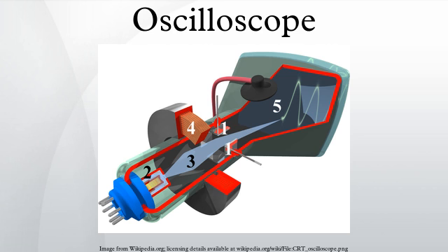A digital phosphor oscilloscope uses color information to convey information about a signal. It may, for example, display infrequent signal data in blue to make it stand out. In a conventional analog scope, such a rare trace may not be visible.